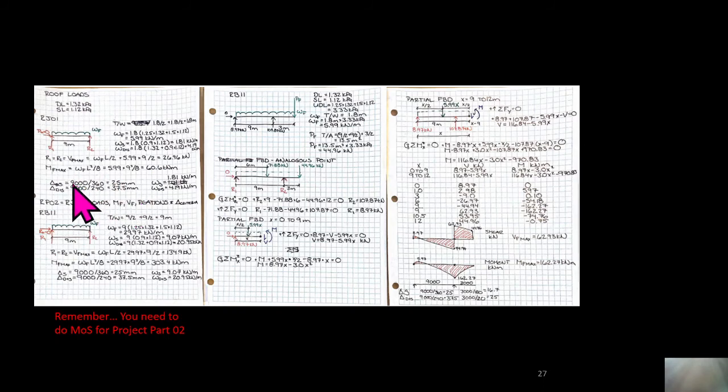We know that we have maximum allowable deflections. For snow alone, it is the length divided by 360, or 25 millimeters. For dead and snow, it is the length divided by 240, or 37.5 millimeters. And we know that we tracked these serviceability loads to use with this. We don't know how yet. That's the thing we're going to look at next year when we do Structures 2. But you will need to know how to calculate all of these things right here pretty quickly going into next term or next year.